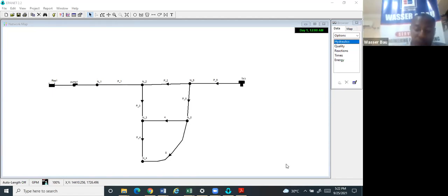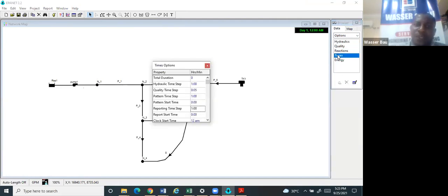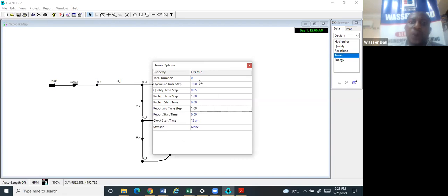Okay. Thank you. Now, some of you asked me a question. We created a pattern and we say 6 hourly pattern, and we put in for 6 hours. So now we're going to go to times. Go to options. Go to times. Then you click on times. A dialog box will open. It will ask you, how long do you want to run this simulation? I want you to put 48 hours or 72 hours.